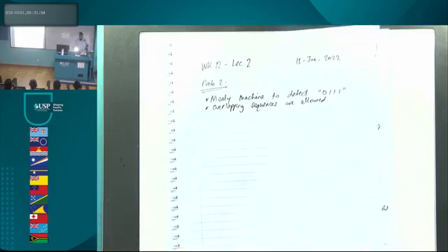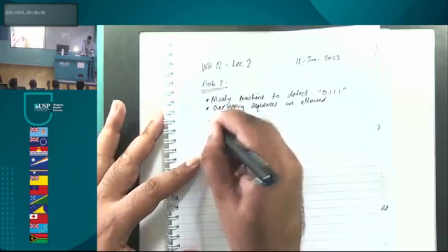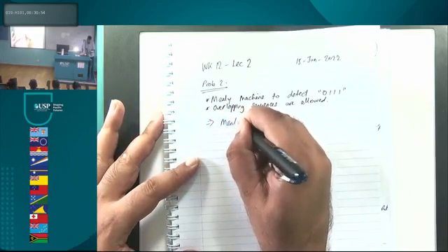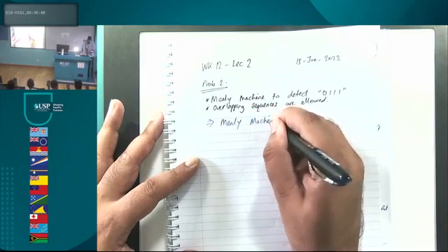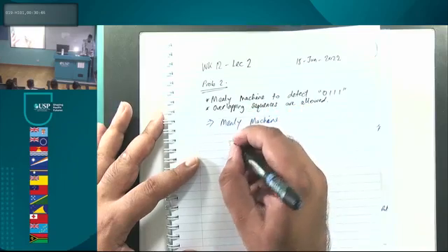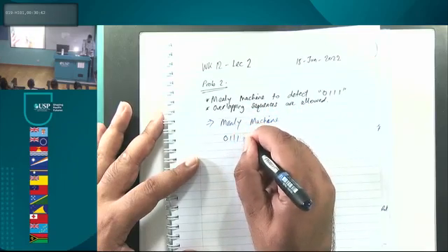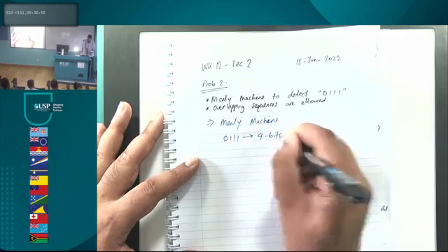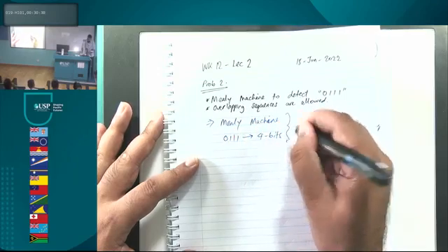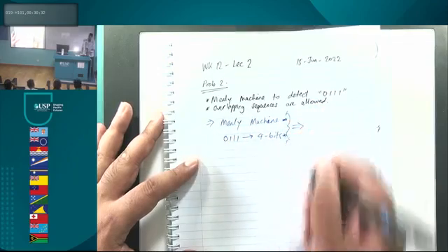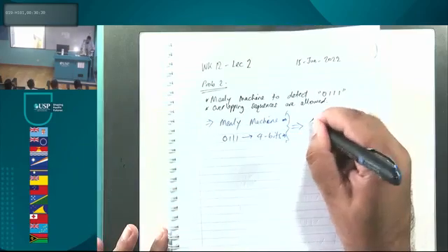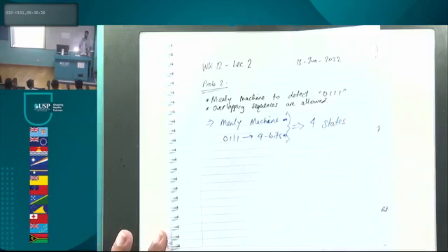Okay, let's go ahead. So we've got to detect 0111. It is a Mealy machine. Let's count the bits. 0111 is 4 bits. Because it is a Mealy machine and we have 4 bits, that means we need 4 states.